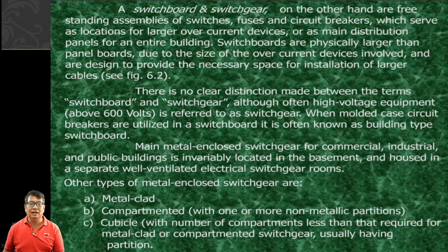Switchboards are physically larger than panel boards due to the size of the overcurrent devices involved and are designed to provide necessary space of installation. Okay, there is no clear distinction between the two, switchboards and switchgears. Anyway, yun po yung assembly ng mga protection natin, no? Is referred to as switchgears, no? When molded case breakers are utilized in a switchboard, it is often known as building type switchboard.